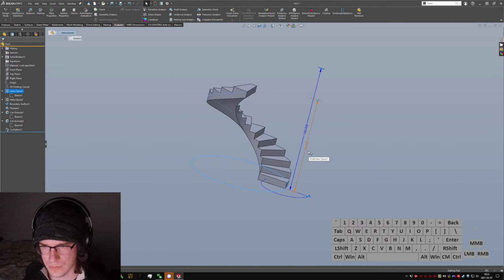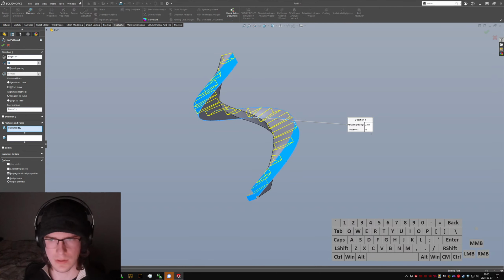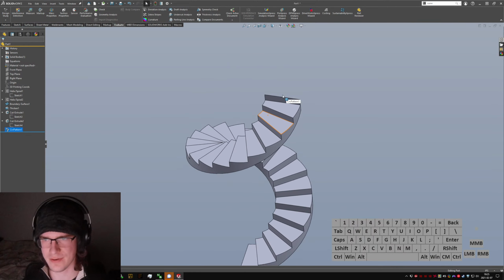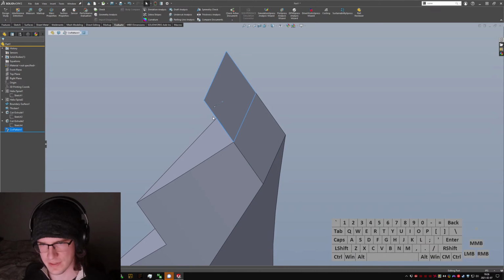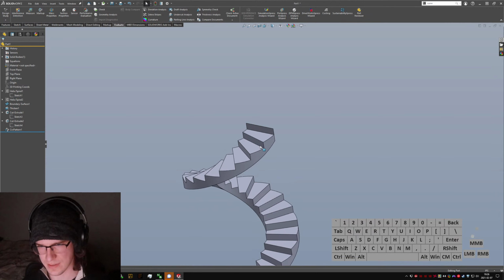We can come in here and say, instead of 15, give me whatever the height is here. Give me D3 at helix spiral 1 divided by 8. That should work. Equals D3 at helix spiral 1 divided by 8. Yeah, there we go. Mostly dynamic. Not quite perfect. It's still got that edge face up there. Not really sure why it's doing that. It's just going to be like that, I think.